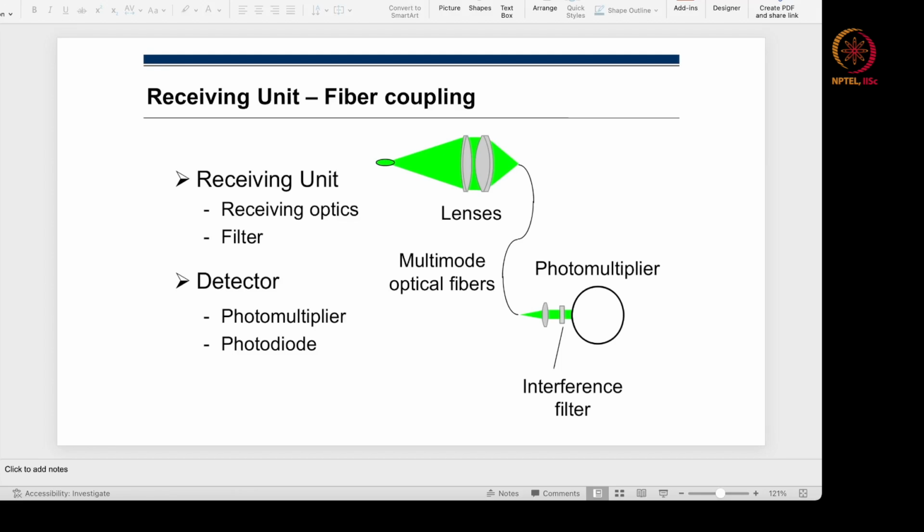Gaussian beams require a special kind of focusing, and the more the beam diameter, the tighter the spot you can focus it to. As a result of that, you can get a very tight volume. And here we are essentially looking at the beat or the interference so that we can calculate the velocity of the particles. And the particles, remember, they follow the flow field. So we stop here.